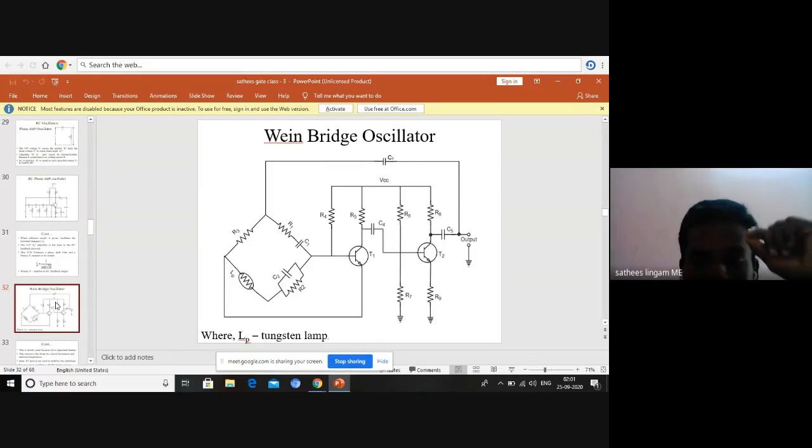You got it? So here transistor T1 is used as an amplifier, then transistor T2 is used for the invert operation, positive to negative. A common emitter amplifier normally gives this: if you give the input supply positive to negative, then on the output side you will receive negative to positive. So just a 180-degree phase shift signal we receive on our output side.